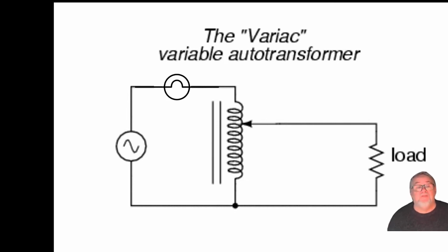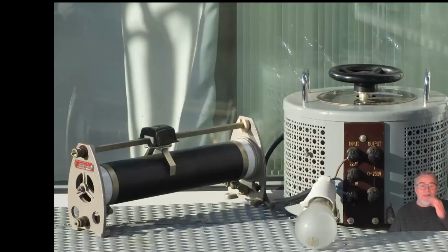And if I go back to that photograph, you'll notice that there's a bulb there. It's not just putting the picture for scale. That bulb is actually a 60 watt bulb in series with that Variac. What happens now is when I switch that Variac on, the Variac's a short circuit. So I've got a 60 watt lamp across the mains, so it lights up.